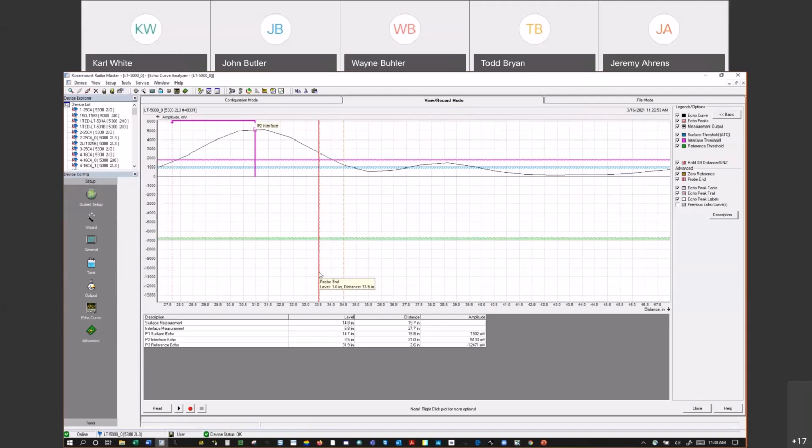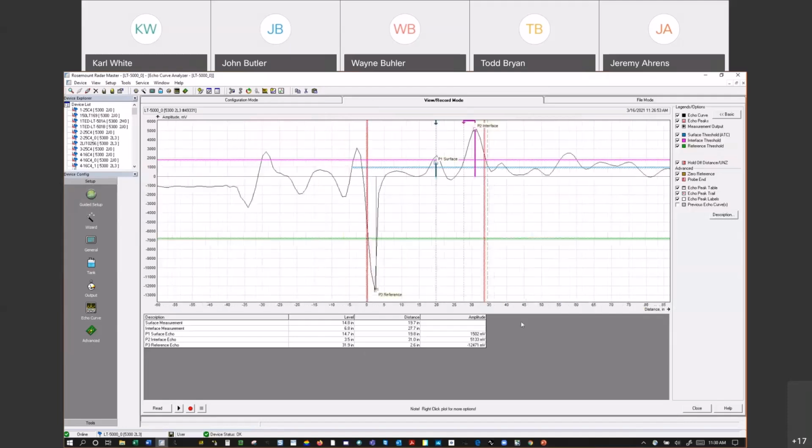You can fix that. If you have to have it show 0, then just make your probe length the same as the tank. The probe length is not that critical. The tank height is the one that really matters. I've seen this a lot come up. And another solution is you can order these with the 2-inch tall weight, right? And then you can get that 6 inches down to like 2.5 inches. So if you order the short, stubby weight, that can move that down a little bit. Yep.